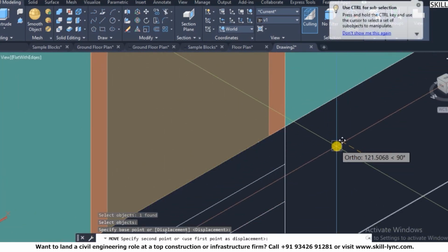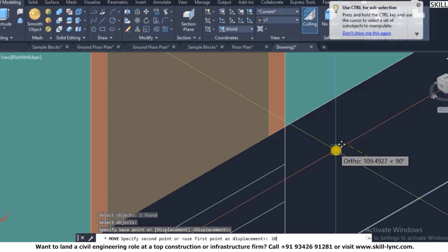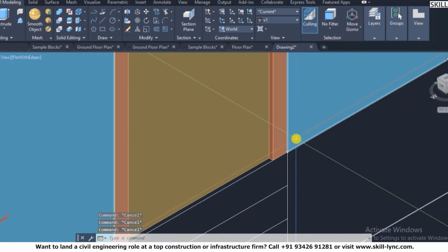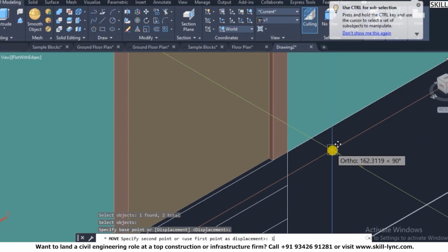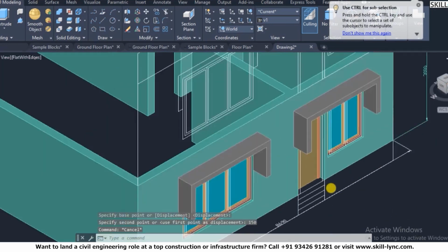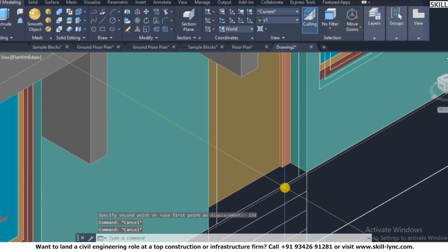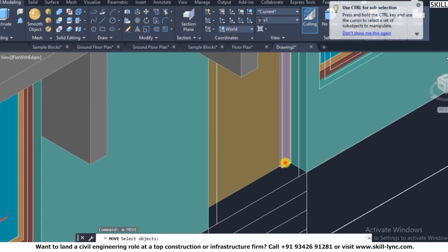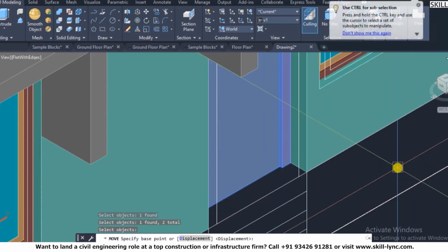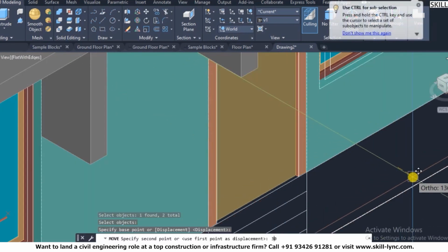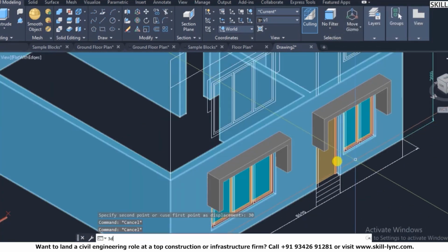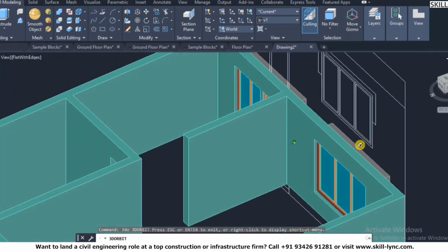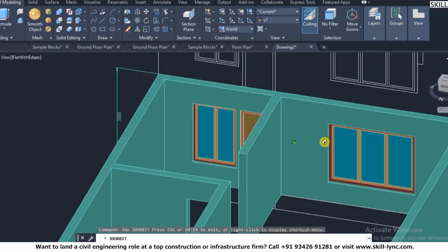So just go towards 20, not -20, and then overall this frame you can move around 150 mm, so that a particular depth happens. Just push it forward, let's say 30 mm forward, so that it does not go beyond the wall section lines. Okay, that's fine.